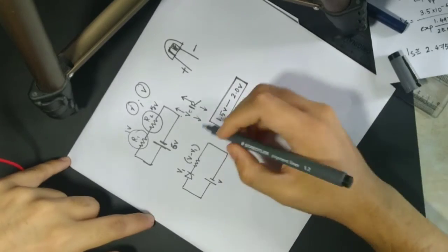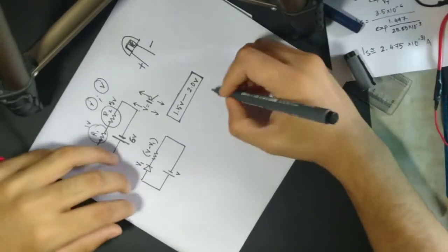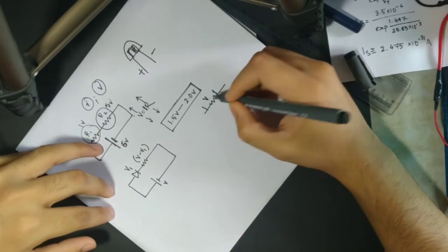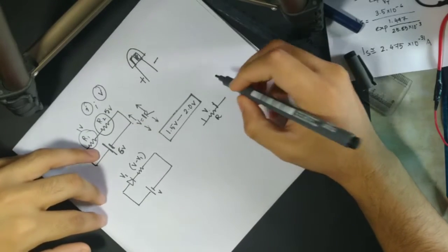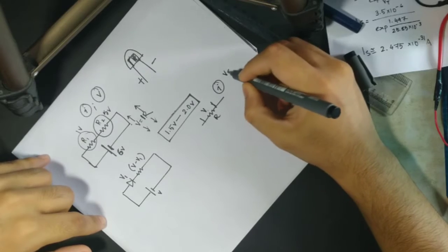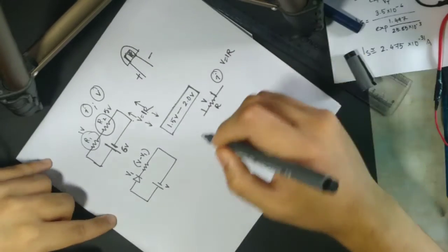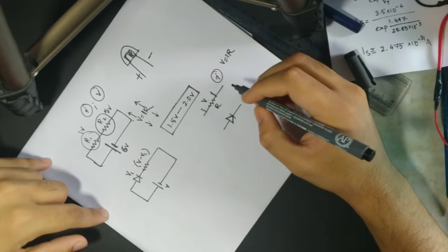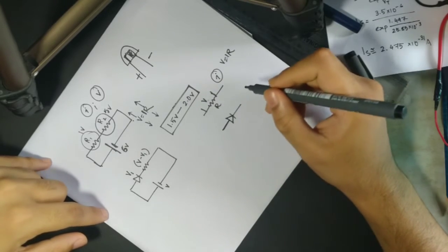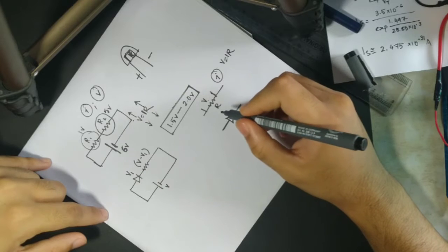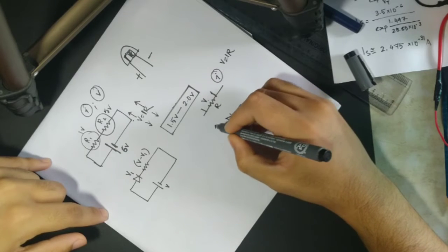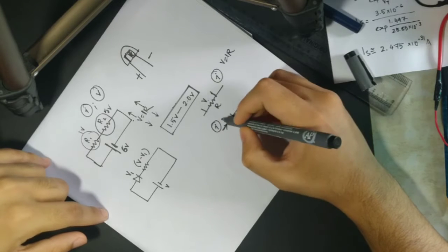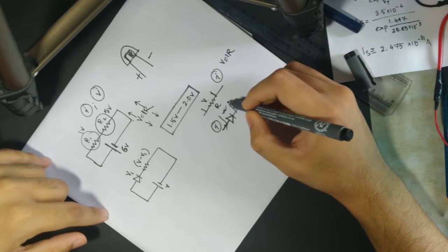Now see, for a resistance, if we find the voltage drop V and we know the value of R, then we can easily say what is the current using the relation V is equal to IR. Now we also need some relation for the LED, so that suppose someone asks me that I am giving a current of I amperes through the LED, what will be the voltage drop across it?